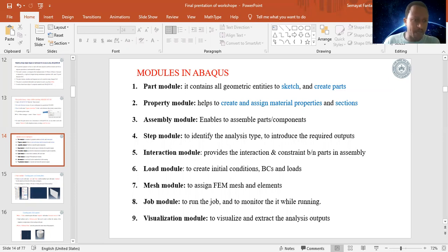And the rotary inertia properties remain blank. Okay, then we can see some green color here that indicates the concentrated mass or lumped mass. Okay, then the other materials, the material for the plate and the material for the interface, should be created using create material, give material